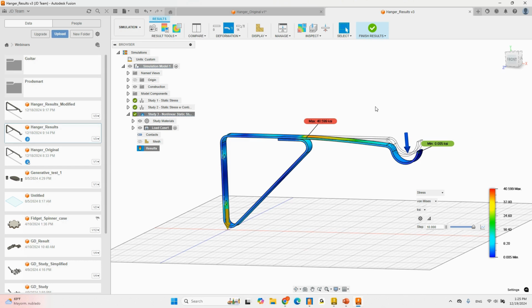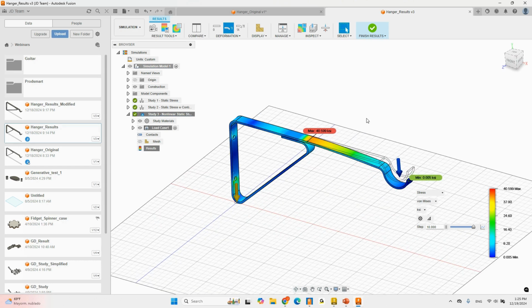All right. Of course, we need to contrast. This would be like the first conclusion that you would get by analyzing the results. But of course, you need to do validation, verification as well. You need to run a mesh convergence analysis. You need to check that the solution you're getting is converging to a single solution.